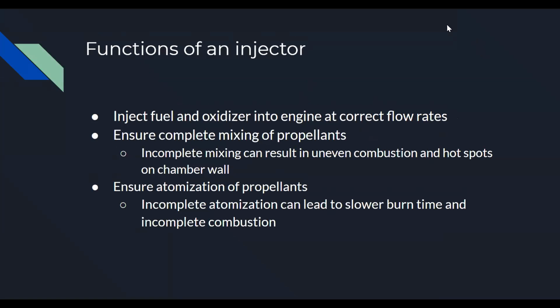So the basic function of the injector is obviously to inject the fuel and oxidizer into the combustion chamber and allow the combustion of the propellants. So the injector needs to make sure that that happens at the correct flow rates of your fuel and oxidizer.